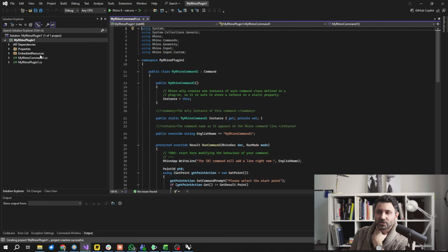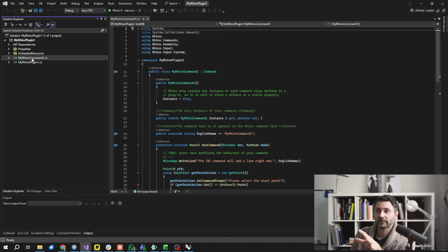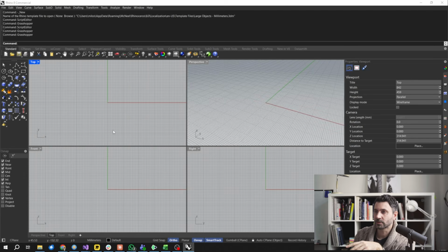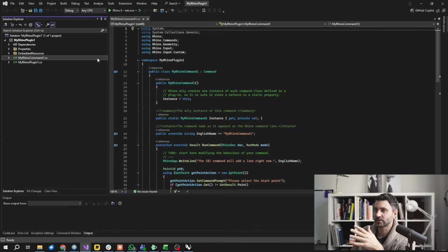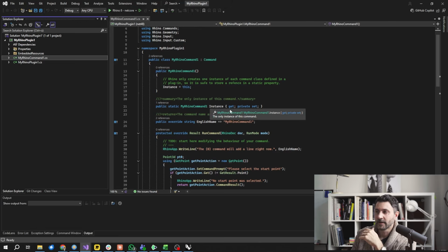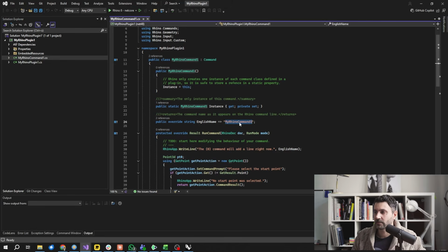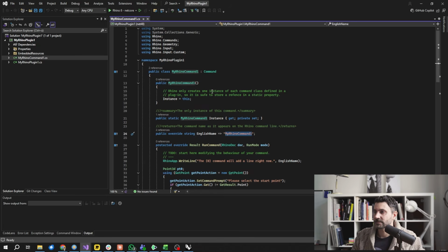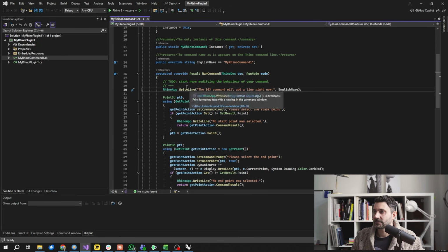And see, like you saw there with the Grasshopper and the component, now in a Rhino plugin you don't have a component, you have a command, right? So now you can execute that command, you can call it from here. Or you can create your own toolbars and so on, but those toolbars and these icons do nothing else. They just call commands, and those commands are registered here in Rhino. And then you can see that I basically have the name of my command, which should be unique. There's some IDs in the background. And then this is a sample command that executes some code.